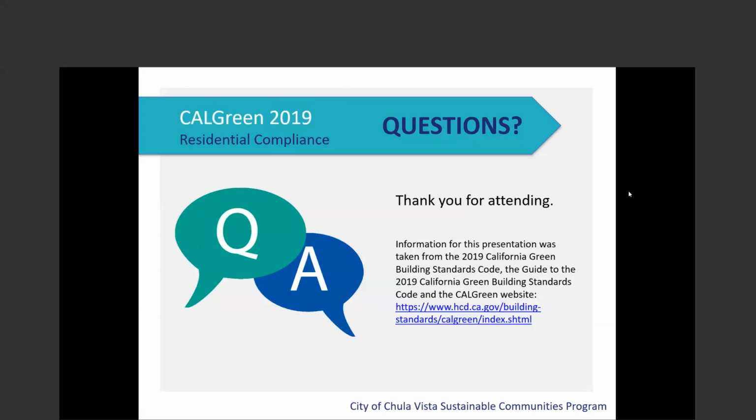That's where you would go to a high volume tankless. There are point of use tankless water heaters that are electric that do have a place. When you're looking at the energy code, a lot of it is about trade-offs. And so you can use the point of use. It tends to show up more in commercial uses or in ADUs, for example. But you're not going to get the efficiency of an electric resistance tankless water heater that's going to provide any real benefit to your overall energy performance.